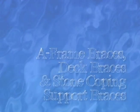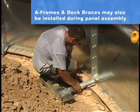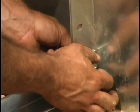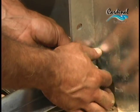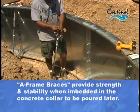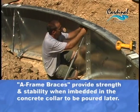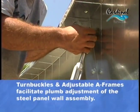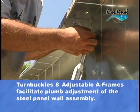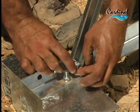Once all the walls are aligned, level, and secured, install adjustable A-frame braces and optional deck braces and stone coping support systems. Secure the lower component or short angle of the brace at the bottom by bolting it to the bottom of the panel. Then, attach the adjustable support, in this case a turnbuckle, at the top of the panel. And finally, secure the support to the short angle at the bottom.